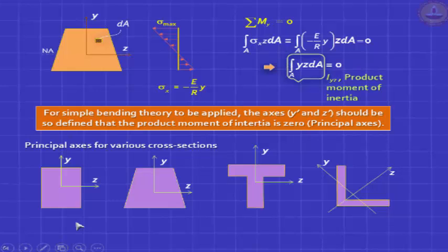So you'll find that in a rectangular section, tapered section, T section, I section, the symmetry with respect to y axis is usually satisfied. But in a channel section or an angle section, which you use commonly in steel, it is not satisfied. What does this mean? This means if I load this, let's say the beam is like this horizontally and I load it vertically, it's not going to just bend vertically. It's going to bend horizontally also, because it'll have components both about z and y axis. Such bending is called unsymmetrical bending.